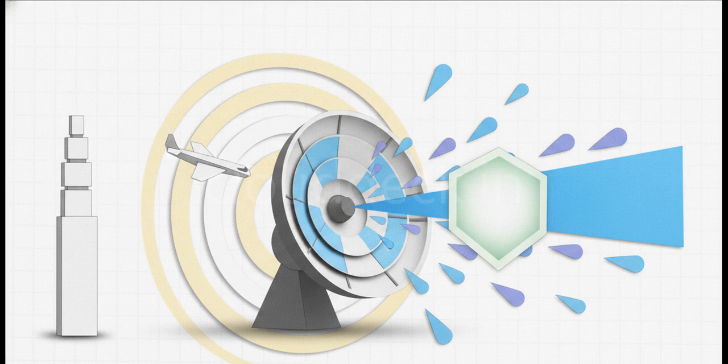Here's how it works. A third pulse, called P2, is transmitted slightly after P1, but it uses a fixed omnidirectional antenna. Because P2 is broadcast equally in all directions, if your aircraft receives a P2 pulse that is stronger than or equal to the directional P1 pulse, your transponder mathematically knows, hey, I'm caught in the side lobe, and it completely suppresses the reply. It's a brilliantly simple solution.